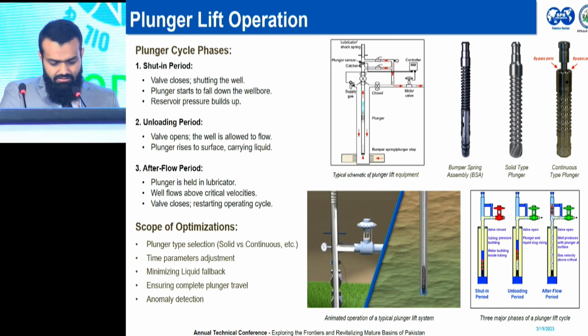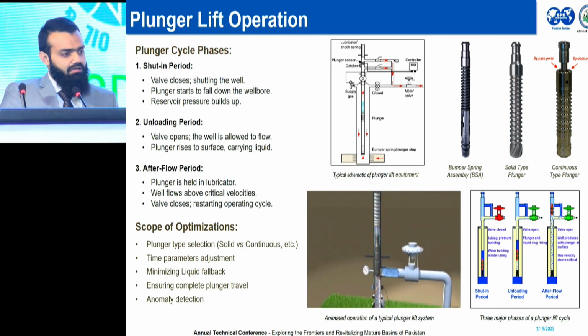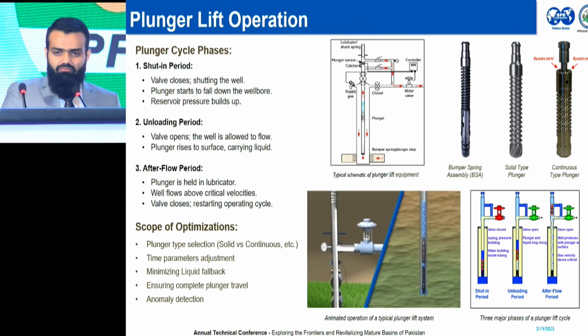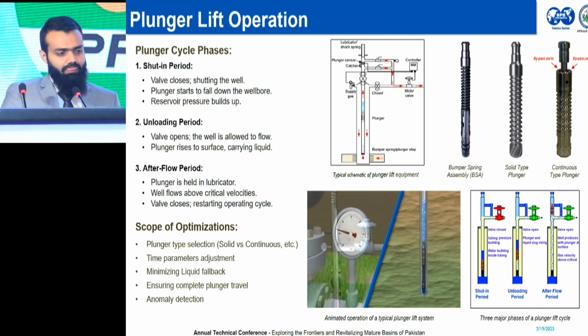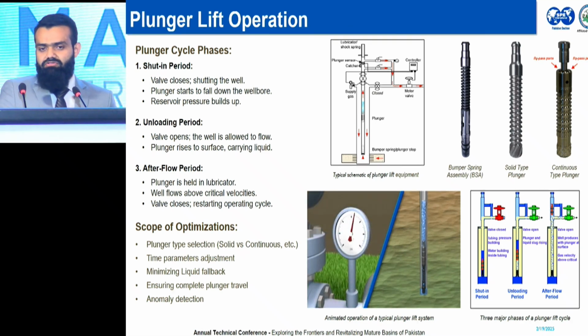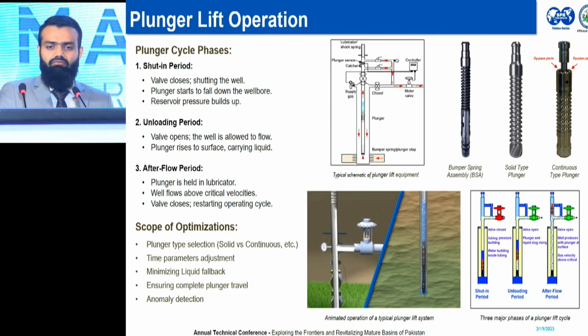These changes may include varying GLRs, declining bottom hole pressures, or some performance issues as well, for example, incomplete plunger travel, overcycling or liquid fallback.